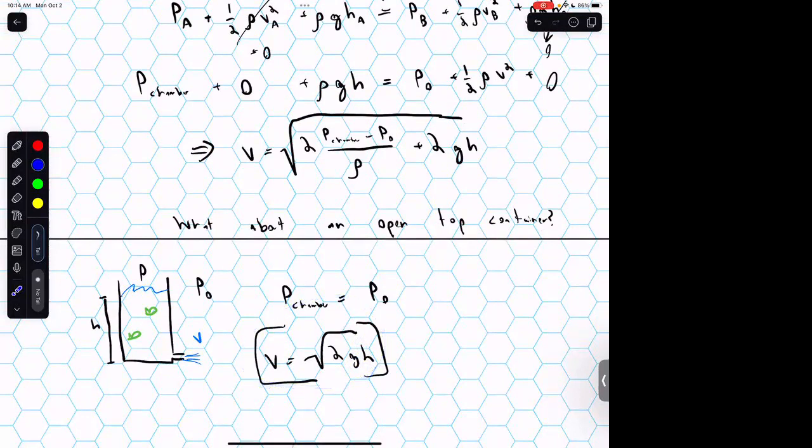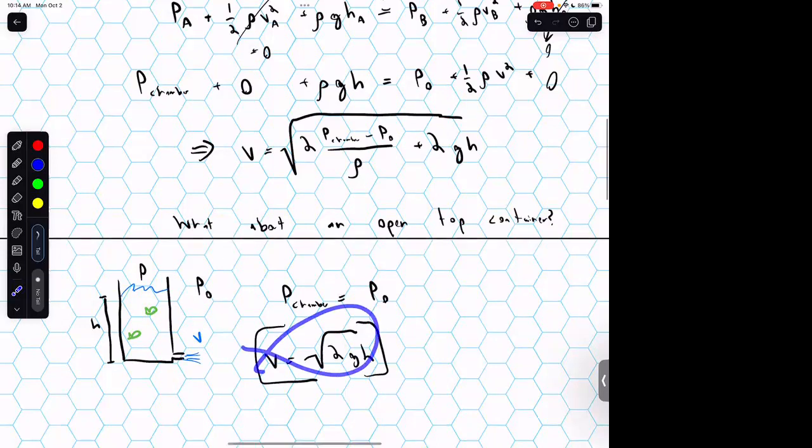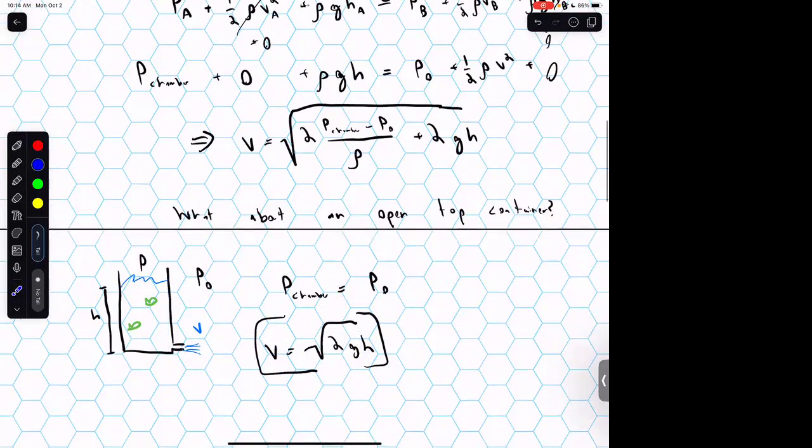And then even as the water level starts to slowly decrease due to water leaving the system, this will hold true. It's just that H will be changing as a result. So this is always true in some sense, but you can imagine over a really long amount of time, this H could actually decrease. Okay, and this expression here, the very specific case where equal interior and exterior pressures, sometimes you'll hear this called Torricelli's law. But remember that you can always derive this just from the original Bernoulli's principle, which is arguably the more general equation that you can use in all sorts of weird settings.